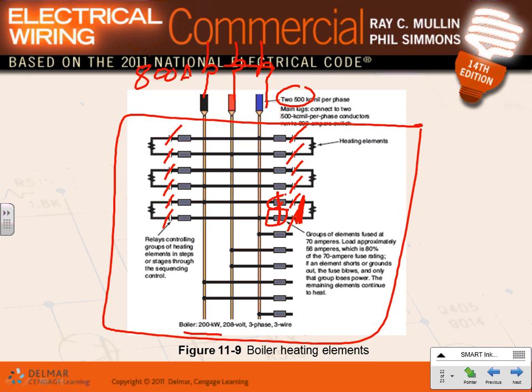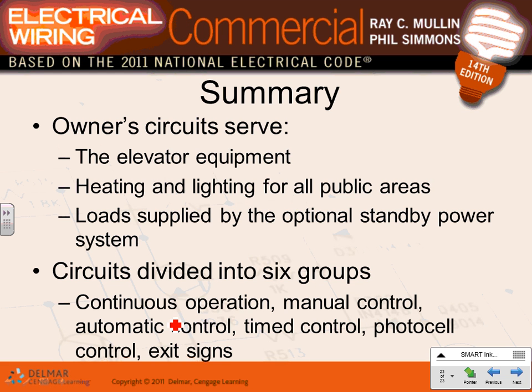No, these fuses will open and isolate this section from the boiler. They section the resistor, so if there's a short circuit in one section, you don't want to lose the whole boiler. So it will open that section, it will alarm, and then the technicians will go there and fix it. Cool, so that's okay. That's all I have for you, guys.